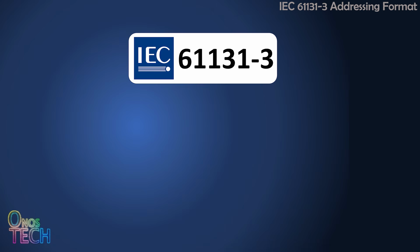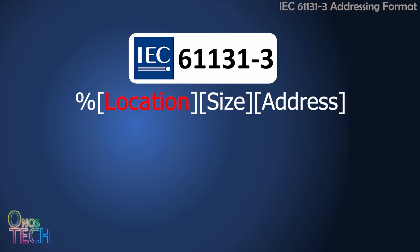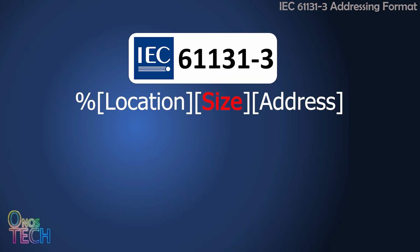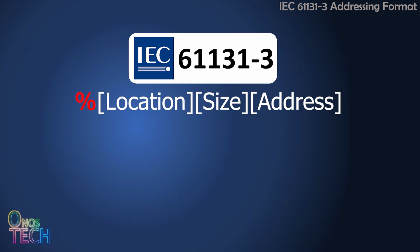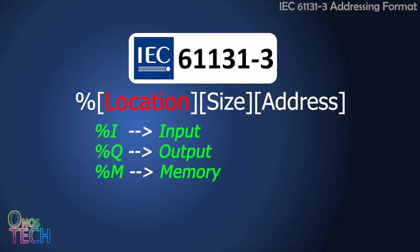Regardless of the microcontroller used, all PLC IOs follow the IEC 61131-3 addressing format, which maps directly to hardware pins and internal memory locations. The PLC addresses follow a simple structure that tells us both where the data is located in memory and how large the data is, whether it is a single bit, a byte, a word, and a unique address. The percentage symbol is the IEC address prefix, and the memory locations can be I for input, Q for output, and M for internal memory.